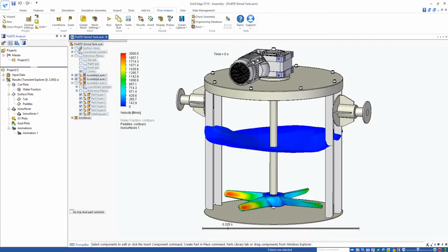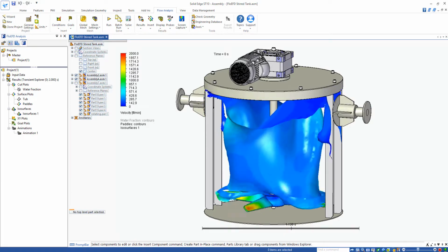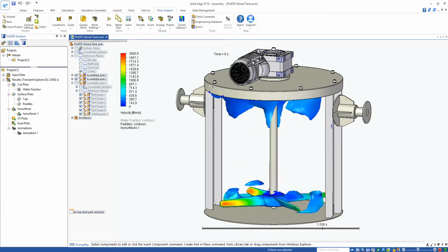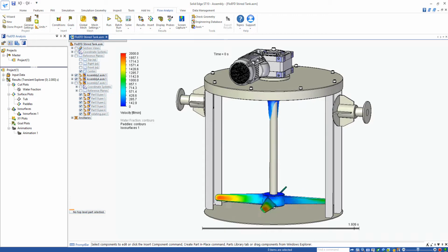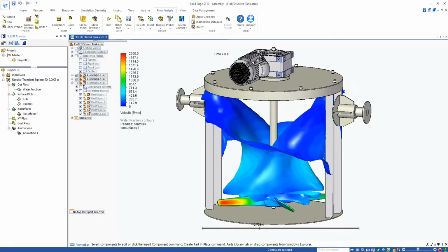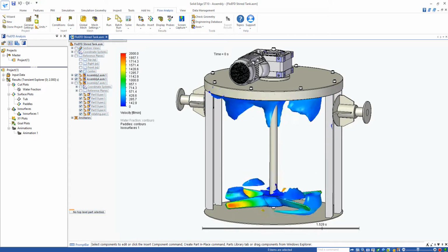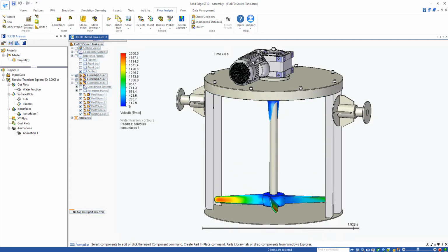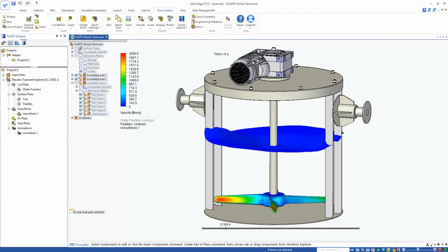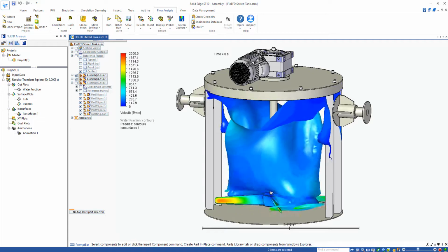Now let's have a look at an Isosurface showing where the boundary of the water lies. This moving surface gives an indication of the mixing plane in the tank. At the start, it clearly divides the two fluids, but as the transient progresses, we can see the chaotic mixing until there is no mixing plane as the two fluids have been homogeneously mixed. Creating animations like this in FloEFD is very simple using the new Transient Explorer feature.